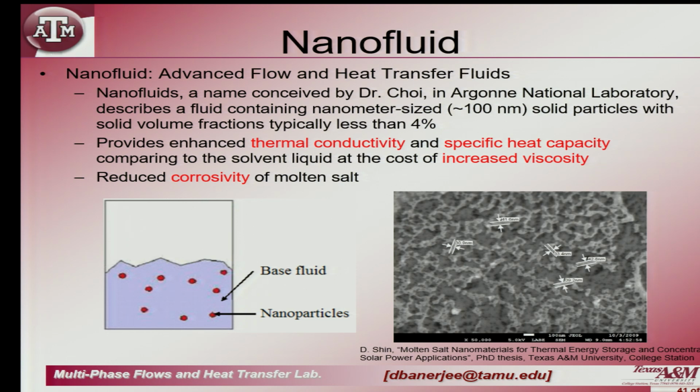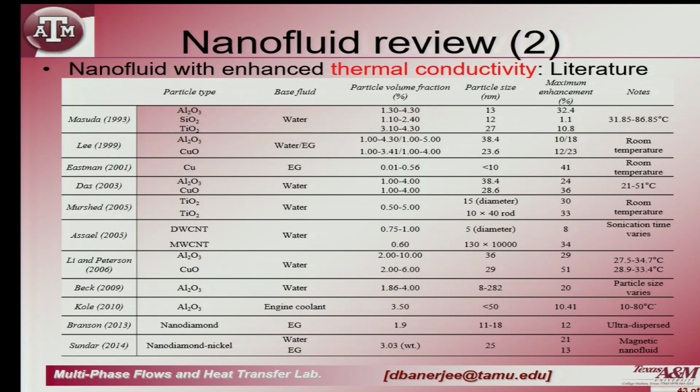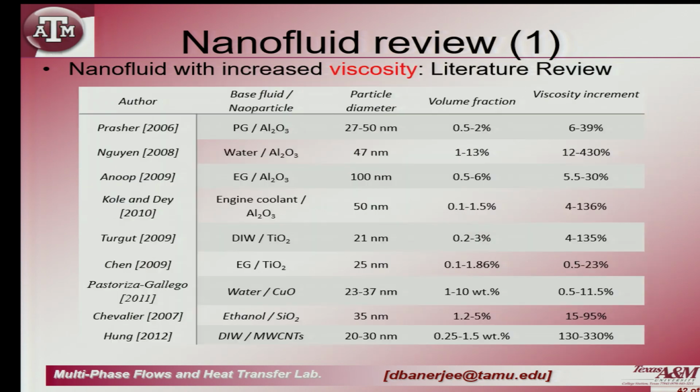Now, why do people care about nanofluids? Well, people have shown pretty high enhancements in thermal conductivity at mass loadings as low as 1%. So, these are all the prior work in the literature showing percentage enhancements in thermal conductivity. And then the realization in the community was, when you put nanoparticles in a fluid, viscosity goes up, as high as 400% in some cases. Your viscosity goes up by a factor of 4.